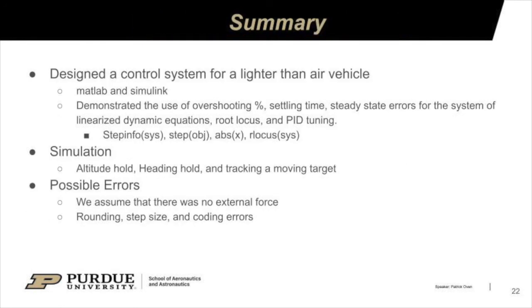Overall, after completing the project, our group has a deeper understanding of designing a control system for a real-world application using MATLAB and Simulink. We successfully demonstrated the use of overshoot percentage, settling time, steady-state errors, root locus, and PID tuners through our MATLAB code using the stepinfo, step, abs, and rlocus functions. For part D of our project, we simulated an altitude hold and heading hold as well as the tracking of a moving target. Possible sources of error in our calculations are the assumption that there were no external forces, user coding, and MATLAB rounding and step size.